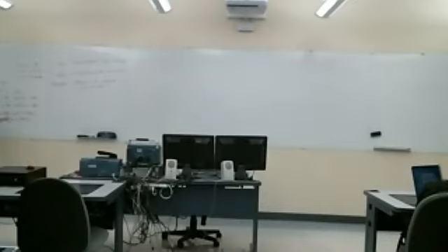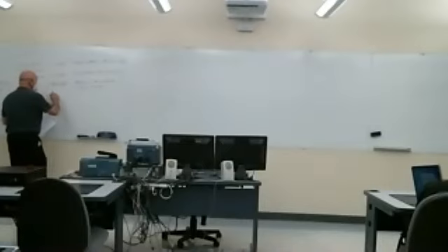So we'll actually be using the debugger in here. The debugger in this integrated developer environment actually works with the microcontroller so that we can single step through the code in our microcontroller and actually see the changes reflected in the debugger.